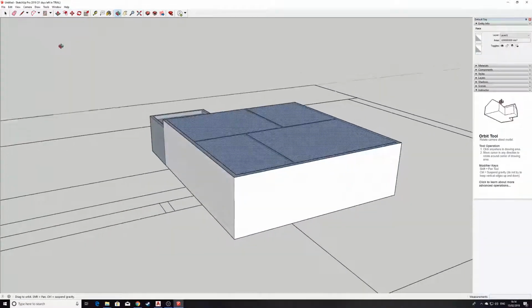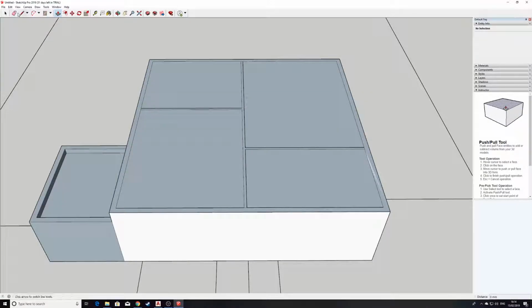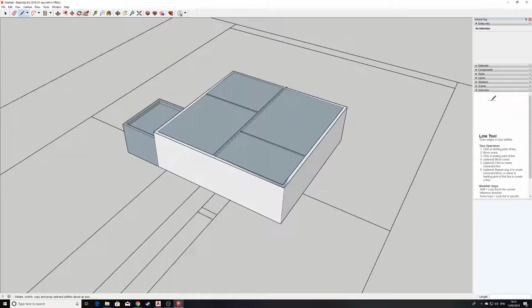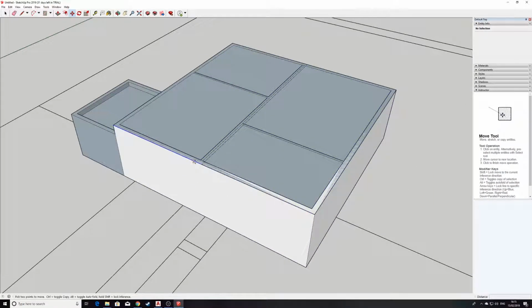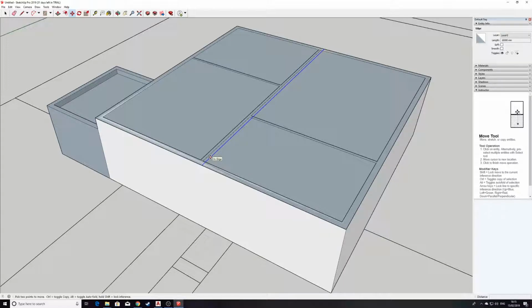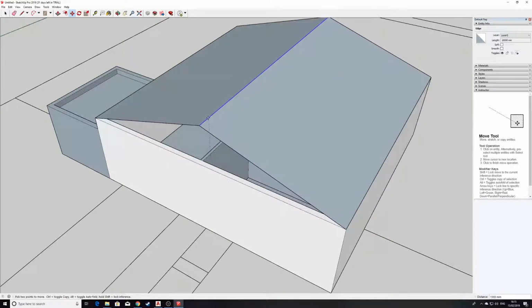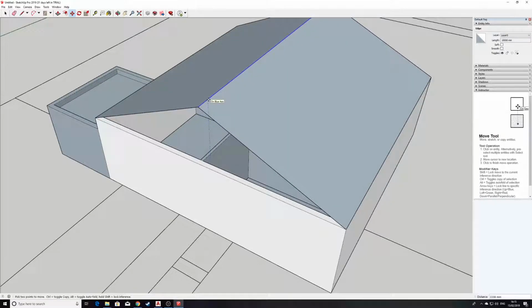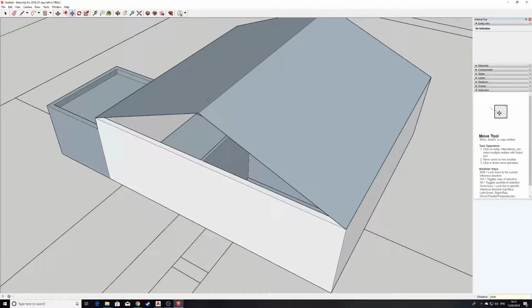Okay, so we're probably going to do a pitched roof here. Similar to Scott's first tutorial, we will draw a ridge. Again, if we can try and find that midpoint there, pull that back along the guided axis to here. Now, if we head up to the move tool again, as long as we are somewhere on this line here, if we select and pull up, we can see that we're on the Z axis there. So if your height of roof is another 2 meters, type in 2000 millimeters, again down the bottom right, you'll see that, and enter.